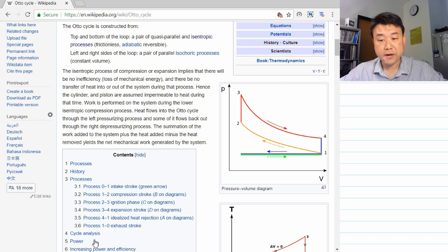And the temperature that it reaches at point 3 is determined by something called adiabatic flame temperature of the fuel-air mixture. You can look it up later, or I will look it up when I do the summary video to compare all these different cycles with each other. Now, from this point 3, high pressure, low volume point, the gas expands adiabatically doing work. And this is what we sometimes call power stroke. This is the part of the engine cycle that actually does work.